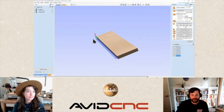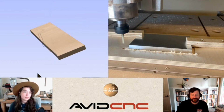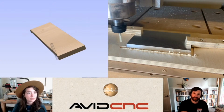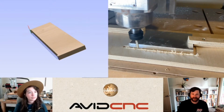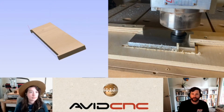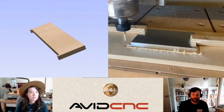We're going to start in this upper left hand and come down and then climb along the south side of our material. And you can see every pass we're doing is a 40,000th step over pass at full tool engagement, and it's always a climb cut. And so we are getting very consistent chips, very good chip evacuation, and we're engaging over a ½ inch of the side of that tool, which means we are getting a lot more life out of that tool than if we were just engaging the first 40 thousandths of the tip.